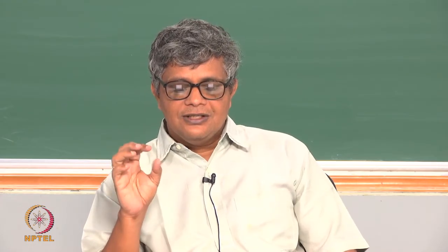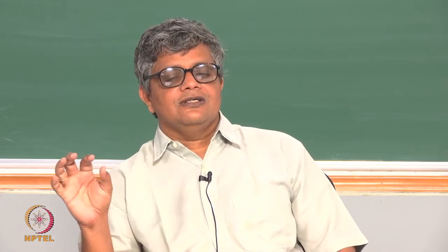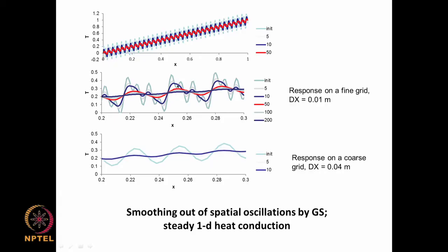So in multigrid, the idea is that you do not have a single grid to deal with to get the solution. You use a fine grid to remove quickly the short wavelength variation, and then you go on to a coarse grid, and then you remove again the short wavelength errors on the coarse grid fast. These things were difficult to remove on the fine grid, because for a fine grid these are long wavelength variations, and that is illustrated here.